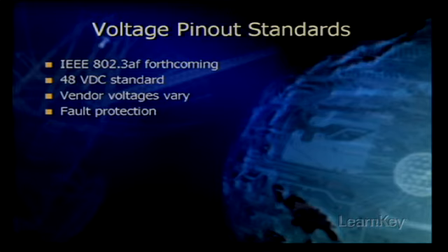But incorrectly wired Cat5 cabling is another example. Cut or crushed Cat5 cabling is another example, in which the insulation of one of the conductors has come in contact with another conducting material that may be carrying power. This can actually cause a fault. During any fault condition, the fault protection that we have with PoE is going to shut off the DC voltage that's been injected into the cable.